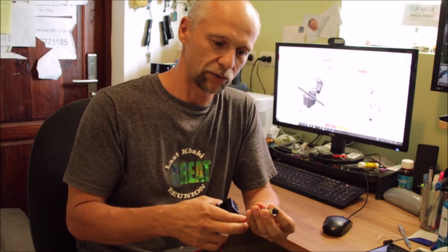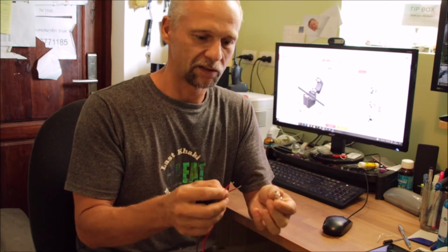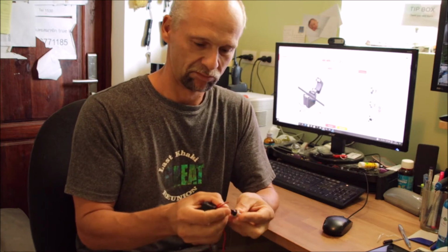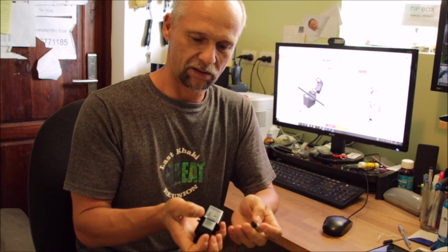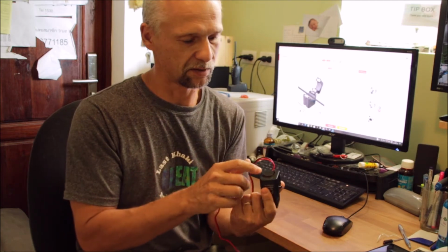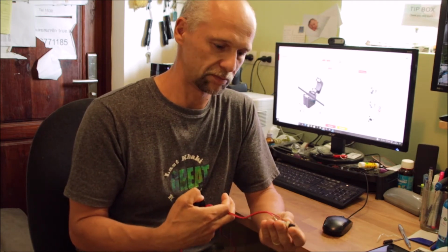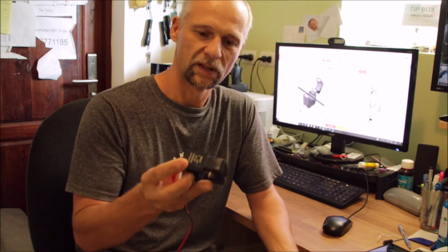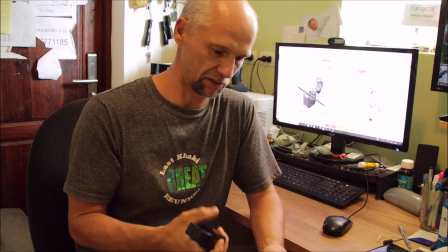and we're going to solder these 2 things together. Of course, I cannot tell which end belongs into which pin, but you know, it depends on the direction, which is marked here about current flow, but it doesn't really matter. If the wire is on the wrong pin, we just need to turn the CT over by 180 degrees, and then it will be correct.